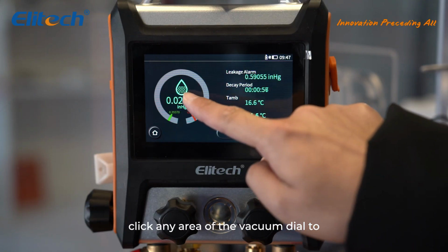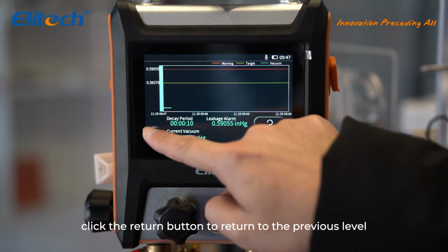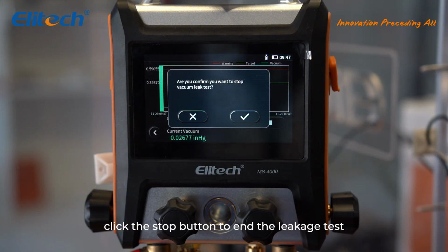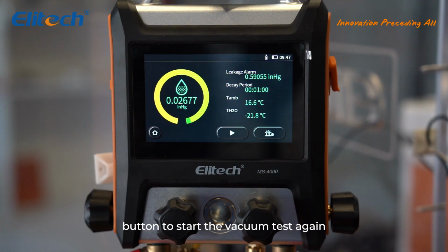Click any area of the vacuum dial to switch to the curve mode. The curve changes will be displayed in real time. Click the Return button to return to the previous level. End the test. Click the Stop button to end the leakage test. New vacuum test. Click the Restart button to start the vacuum test again.